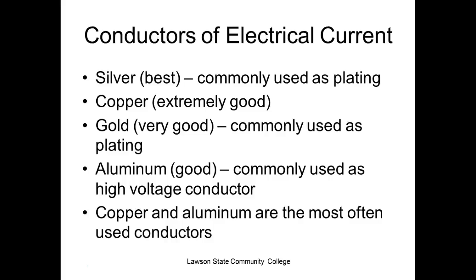And we have people go out there and they'll see these contacts and they'll be gray, and they get out their file and file it down. And then they get down to the copper, and it works real good, but copper oxide is a bad conductor. And now you have something that'll work for a little while, but after a while it stops working. So never file these contacts. They have what they call burnishing tools, which is extremely fine grade.